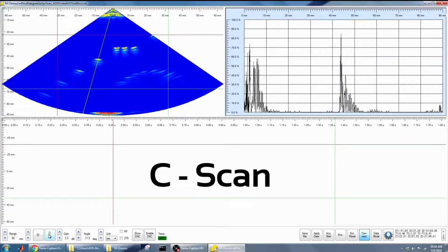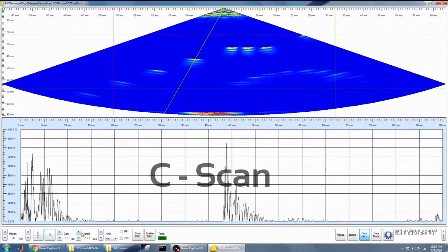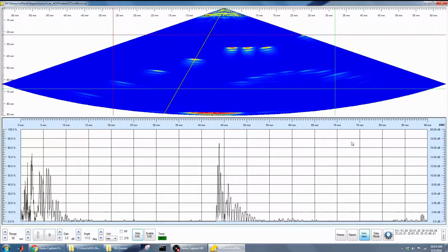The C scan gets filled in as you start acquiring data. This is a top-down image. Distance amplitude correction, or DAC for short, helps with showing things that are further away and displaying a weaker signal. DAC helps these areas appear with stronger signal strength.